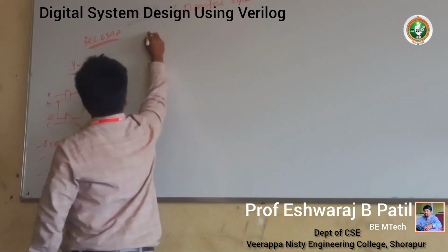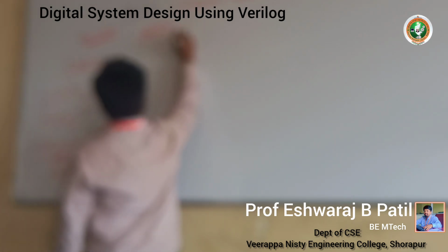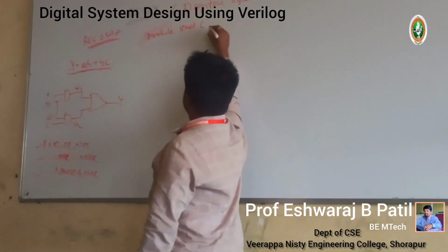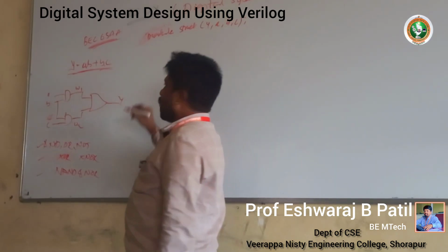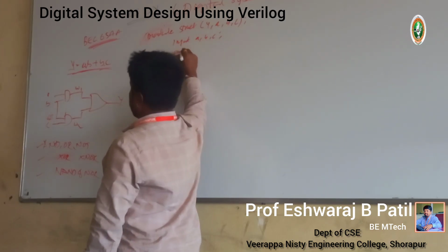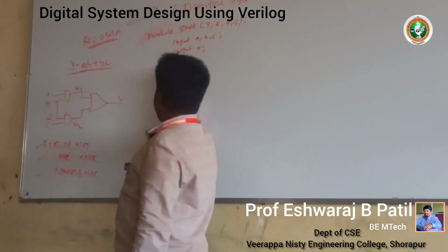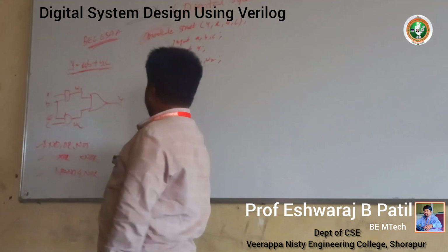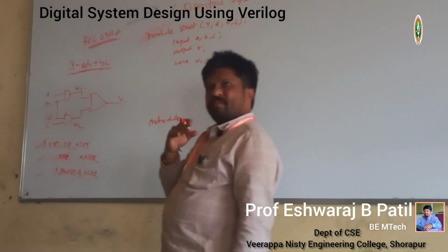Structural model means we consider one module. We can name it any name, say struct. The outputs and inputs are listed here: Y, A, B, C; you have to put the semicolon. Inputs are A comma B comma C. Output is Y, the only output. I have to define the wires also here: wire W1 comma W2, and then the end of the module. It's the skeleton for writing the program.